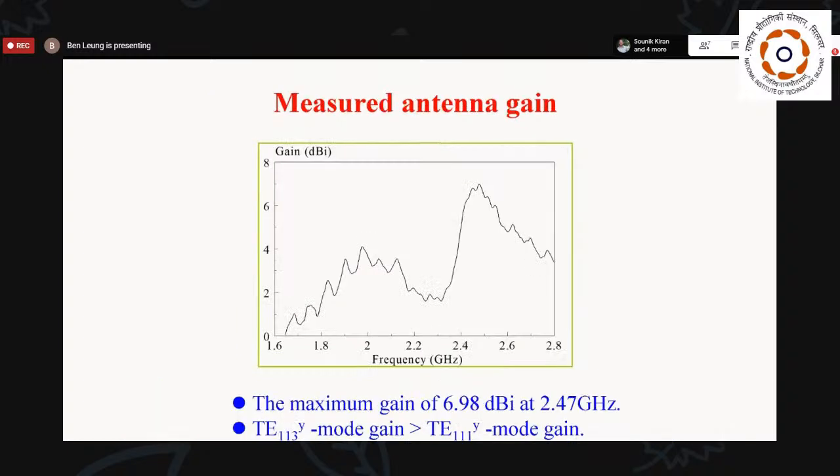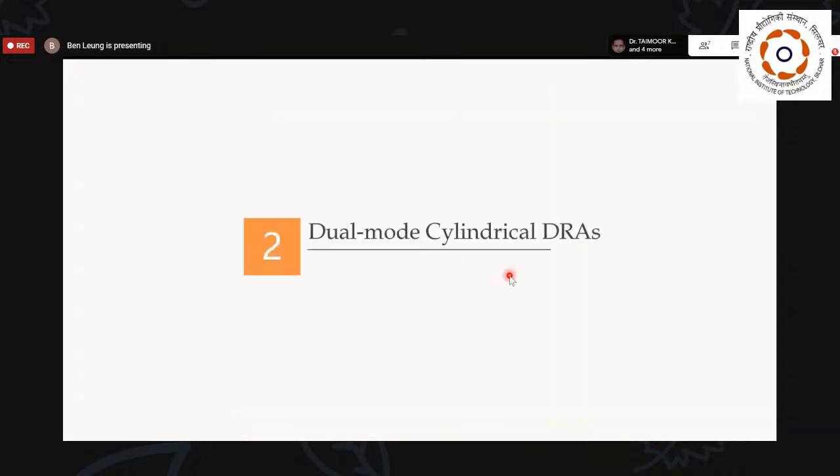Now this is the measured antenna gain. Again, when the frequency is higher, the gain is larger, which is expected. Now, this is the fundamental mode. This is the high order mode. Okay, next, we consider the dual mode cylindrical DRA design.